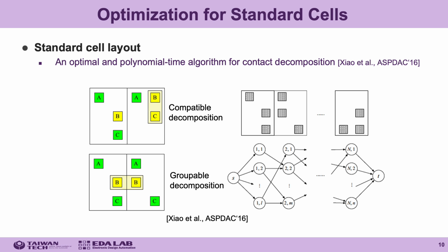For such an optimization problem, a previous work proposed an approach to deal with the contact layer of standard cell-based layout. Since the layout of each standard cell is fixed, it is possible to first enumerate all the coloring solutions of each cell by considering DSA grouping and coloring.